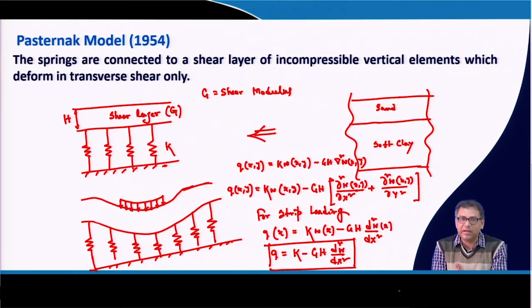and it has already been done by researchers to incorporate the time dependent effect into this model by replacing the spring with a spring and dashpot. That means the spring will give you the settlement and the dashpot will give you the time dependent behavior. So if you replace the spring with a spring and dashpot, then you can incorporate the time dependent behavior into these models also. Then your deformation is not only confined to the loaded region, you will get the deformation outside the loaded region. Then you can incorporate the nonlinearity effect and the time dependent effect. So all these effects can now be incorporated in these models.